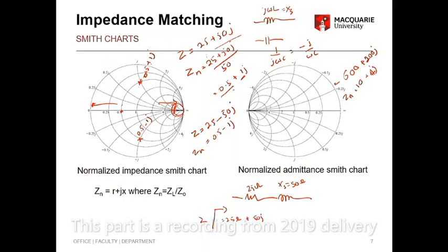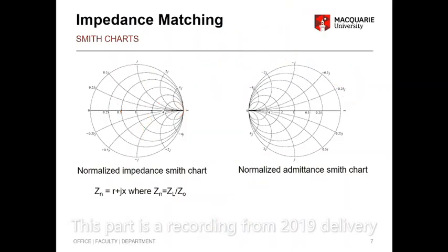So this is called the impedance Smith chart, because I was always dealing with impedances, right? So the same way you can represent admittances, which is on this circle. So you'll notice what's changed here, let me clear this up. What's changed here is the circles came to the left hand side, right? And then the curves now go negative here,